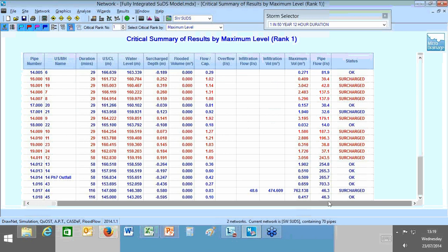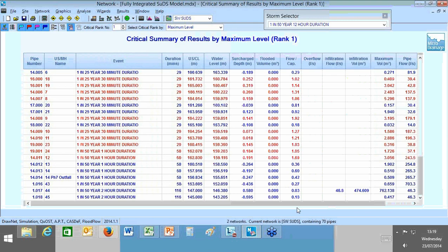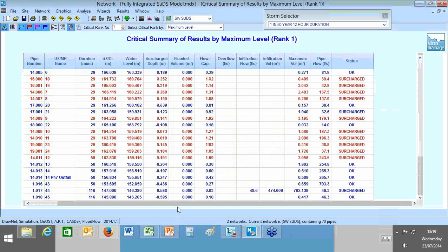And the worst case scenario is we're discharging at a rate of 46.3 liters per second off of the site, and it's the 50-year 2-hour storm duration that's sensitive towards the downstream end of the site, where that complex structure is comprising of the basin with the trench underneath it. How did we limit the discharge off of the site?